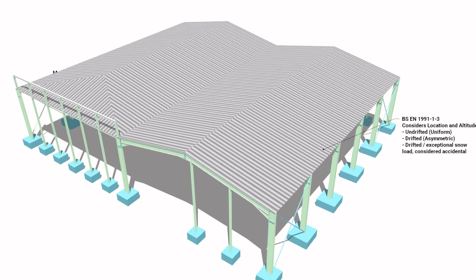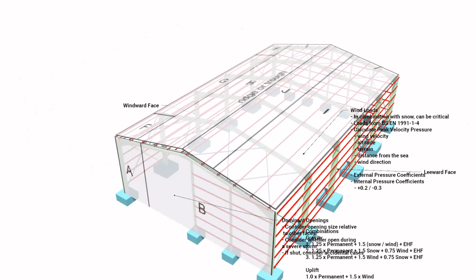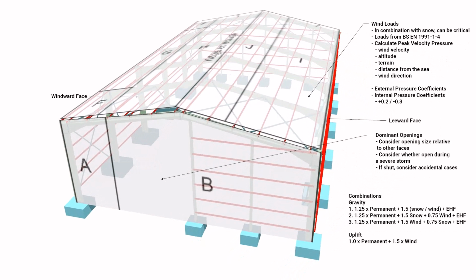So that gives you an idea of snow loading. We can look at wind loads here as well, and we can talk about combinations with the snow loads in a bit. Wind is a significant factor in the design, and Eurocodes combine wind loads with snow loads, which can create greater bending moments than our combined factored permanent and imposed loads. Therefore, in many cases, it can determine our member sizes and the design of our frame.